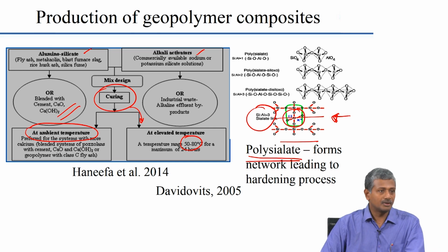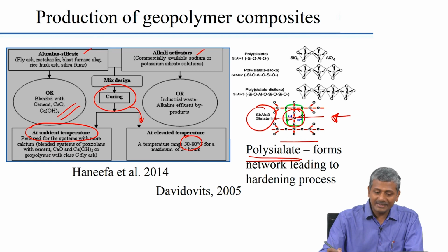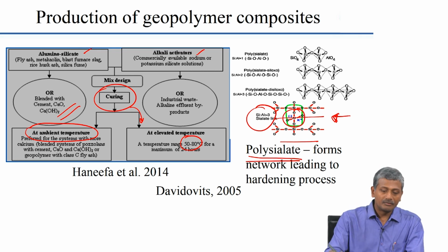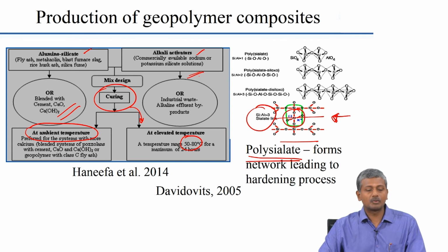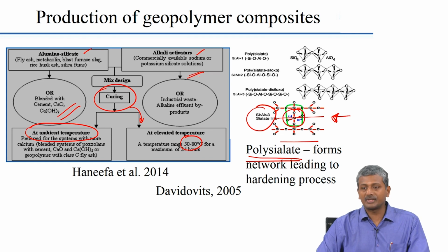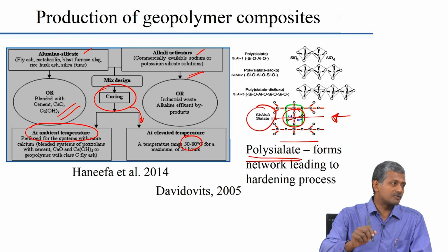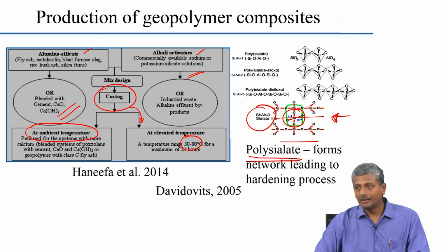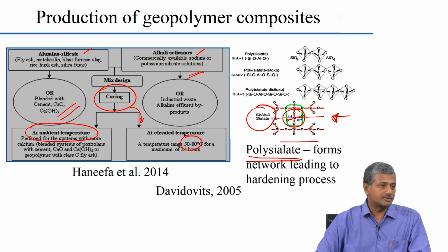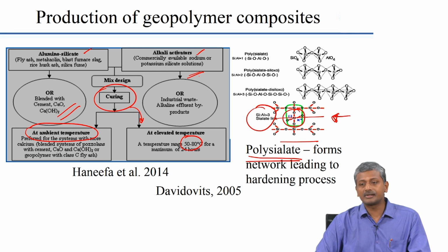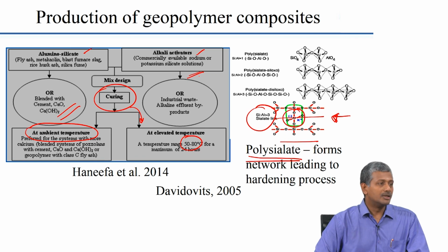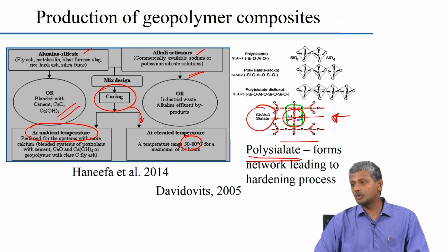But please remember one more thing, that we are adding these alkaline activators, like sodium or potassium silicate, sodium or potassium hydroxide. The incorporation of these activators implies that there is already a CO2 footprint associated with the production of these chemicals. That is something that you cannot neglect. Very often you find in research studies that people simply neglect that and only take into account the fact that there is no cement in this composite. So, you have to remember that the alkaline solution also contributes extensively to the CO2 emission.